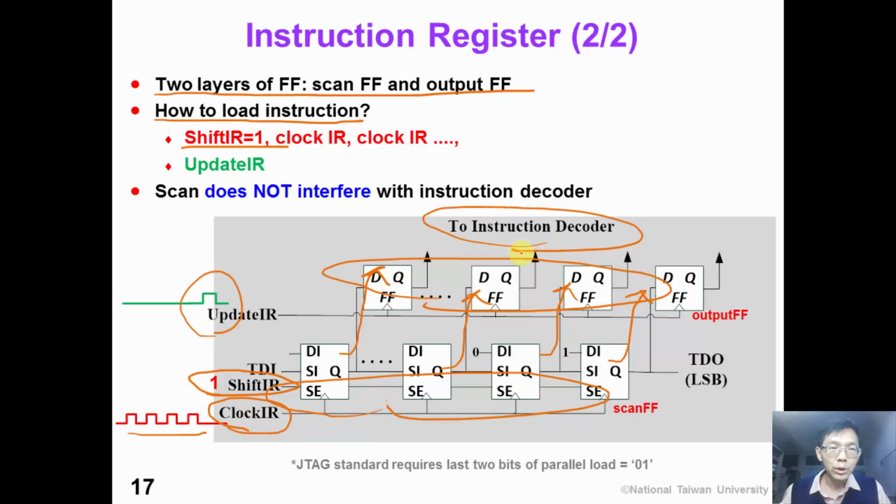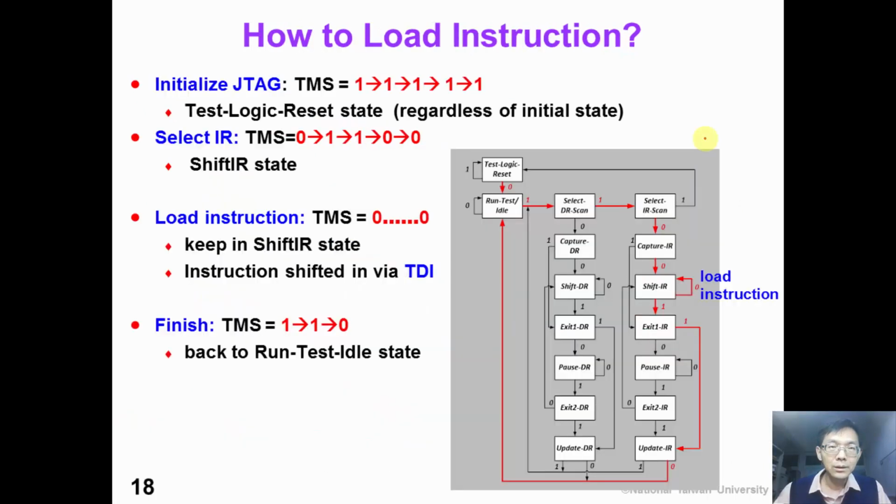We have these two layers of flip-flop design because during the scan operation, we want to isolate the instruction decoder from the scan operation.